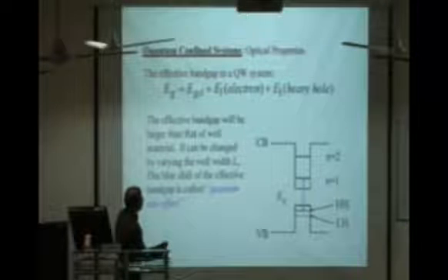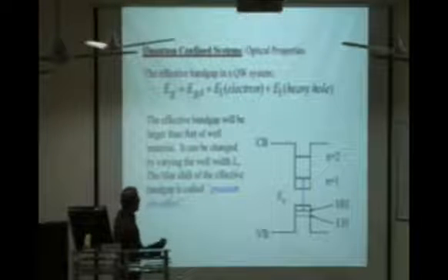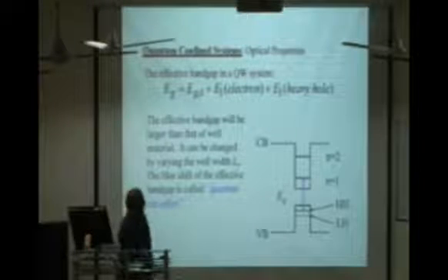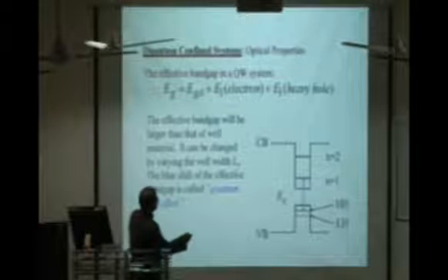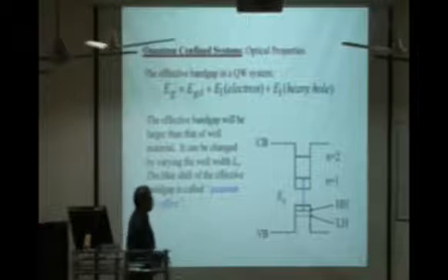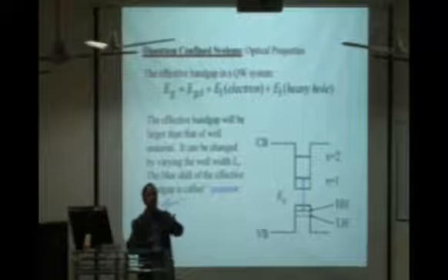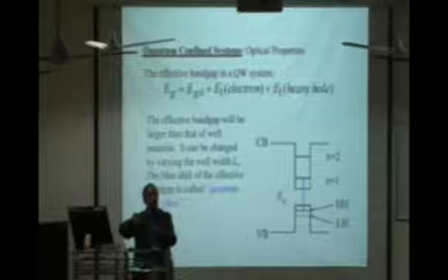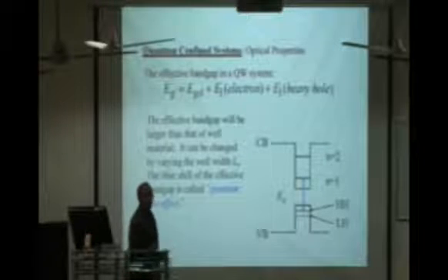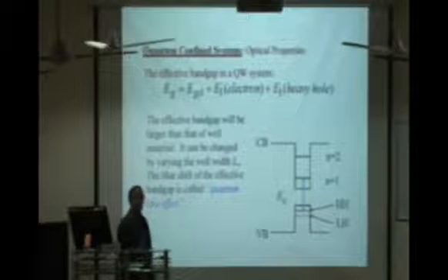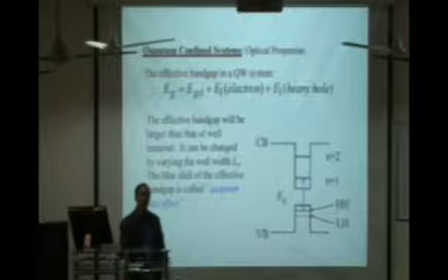So initially we started with a semiconductor with a band gap Eg, and because of the quantization, the band gap has gone up like this. And if you have a very high barrier, you can confine not only the ground state but some of the other states also. In fact, this is also a challenge. It's not very easy to get a combination of a low band gap semiconductor with a high band gap semiconductor so that you get a very high barrier height and confine many energy levels. It is theoretically easy, but experimentally very difficult because there is a lot of problem in the growth of semiconductors with different lattice mismatch.